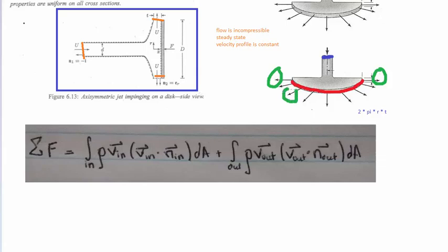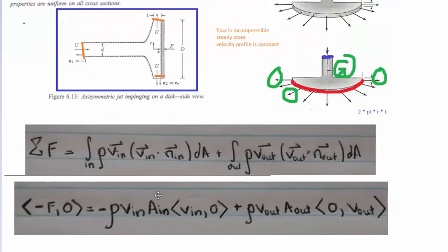Similarly, on the other side of the plate there will be another vector pointing out like this that's going to cancel it out. So your momentum equation in the radial direction will actually come out to 0 because all the flows coming out in the radial direction will have a symmetric partner on the other side of the circle. That's a little hard to realize, but they've already given you the geometry of the picture, so you just need to make one of these positive and one of these negative in the radial direction.